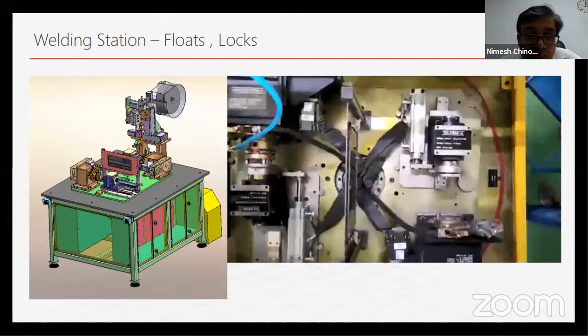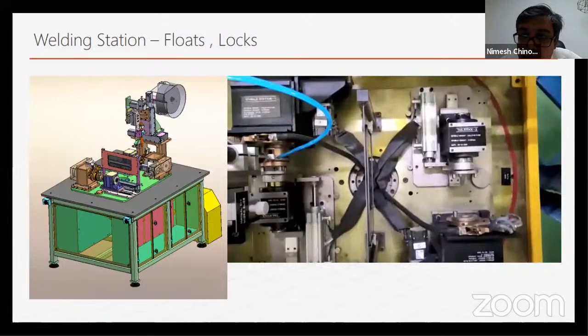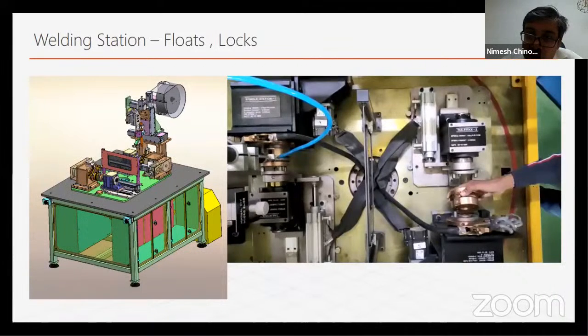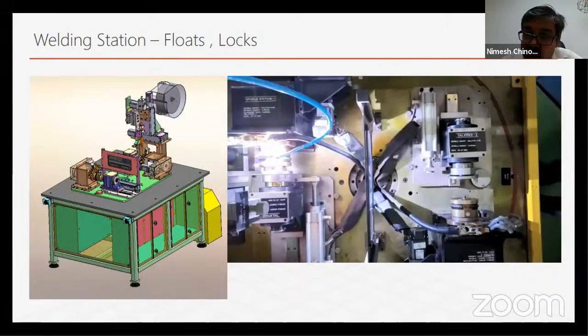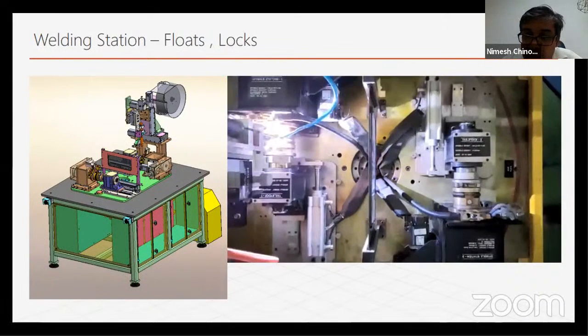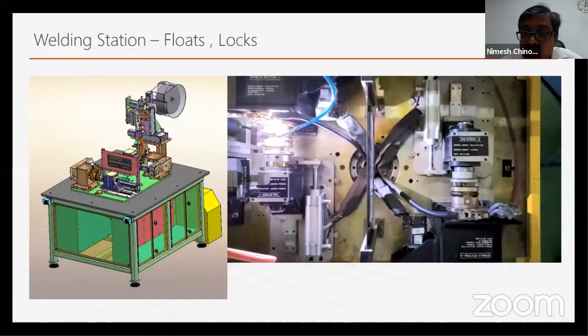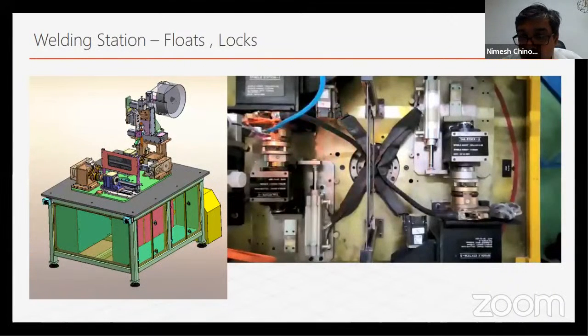Here the weld speeds were as high as 800 millimeters a minute. This gives the operator enough time to put another job into the fixture, check its position properly, and then reload the job for welding. Operator fatigue is minimal. The machine is always in use. The welding is always on. By paralleling this task, loading, unloading, and welding, we are able to achieve more throughput from the same machine.